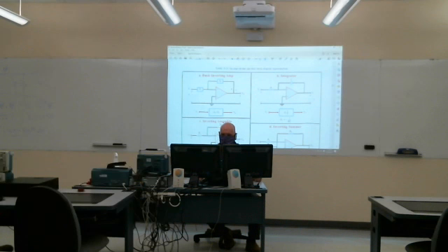Now 1/S is an integrator. Now this is an inverting integrator, but if I do this in LT-Spice, I don't have to use realistic versions of resistance and capacitance. I can use a 1 ohm resistor and a 1 farad capacitor, and LT-Spice is fine with that. Okay. And then that would mean it's an inverting integrator.